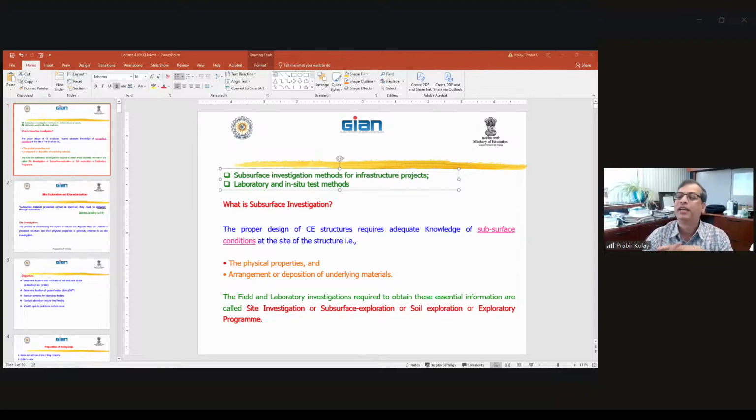Okay. Again, as a geotechnical engineer, it depends on the availability of the equipment. Sometimes, I'm in Southern Illinois, even in the Illinois Department of Transportation, although we know that CPT is better, depending on the site, it is more sophisticated and will give you the result immediately. But people still use the SPT method, it's very common over here. I think a lot of DOTs over here in Illinois, in the US, are using CPT values, and there are correlations as well.